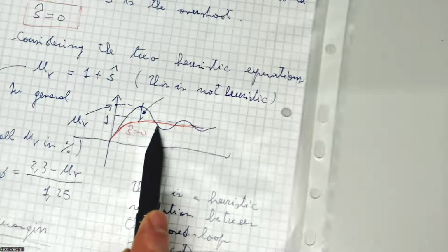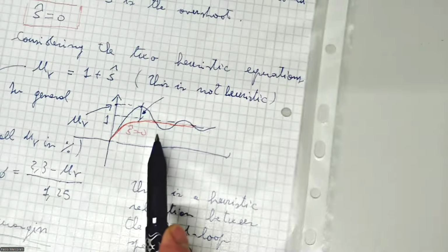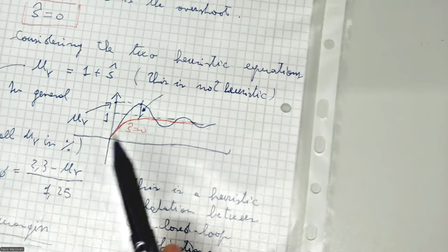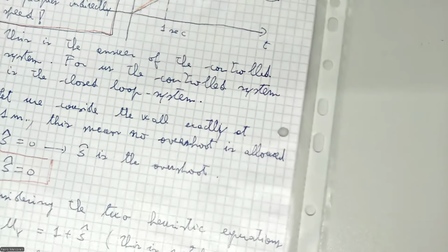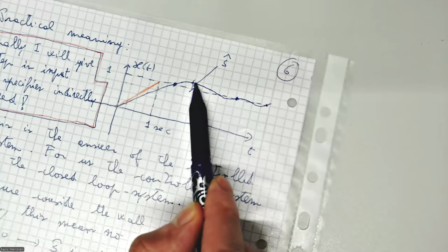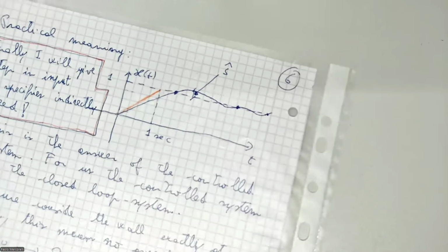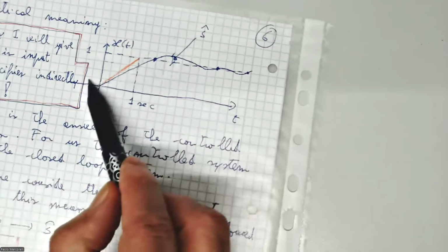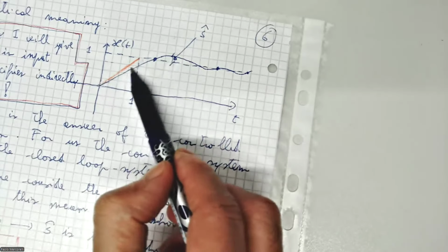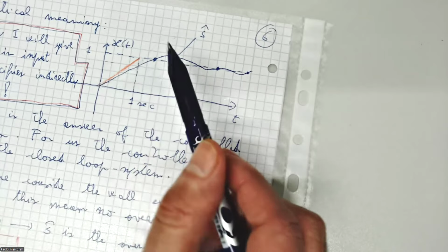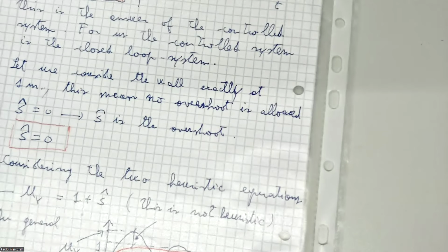If you consider this blue line, which is obtained considering a large enough Ki, with respect to this one here, basically we have a brake action here with respect to here. Of course, we pay a price, because we slow down, let me say, the response of the system. Okay, I would like to stop here. In the second part, we will complete